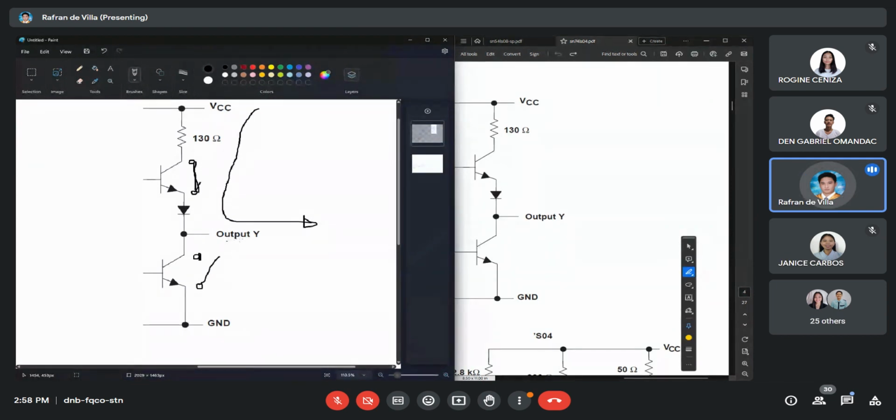Now, look here at the output low, guys. At output low, this one will open. Since it generates a low output, what does it do? When it generates that output low, it simply connects the pin to ground. So the current flows, thus its symbol is reversed. Here it is positive if the output is high, and negative here because of the direction of the current.